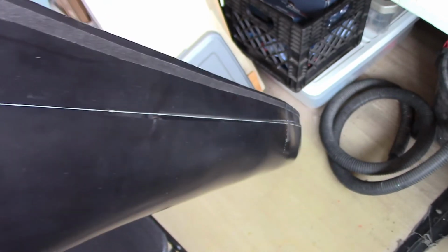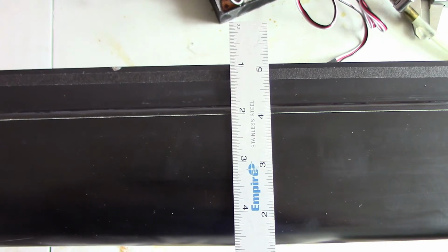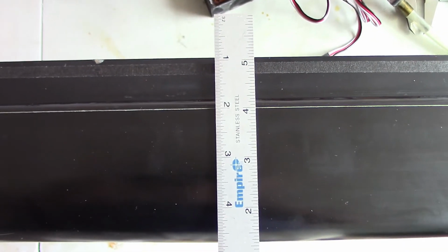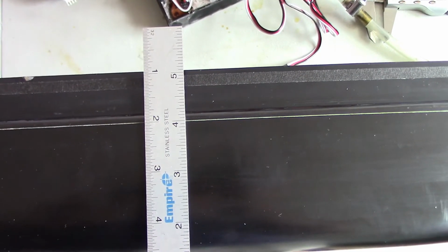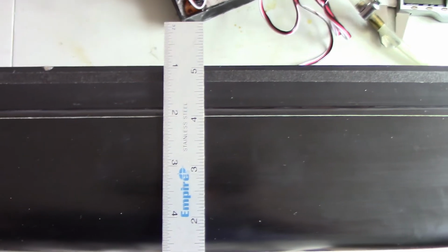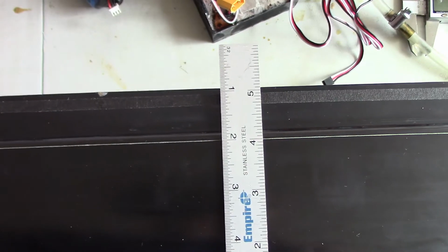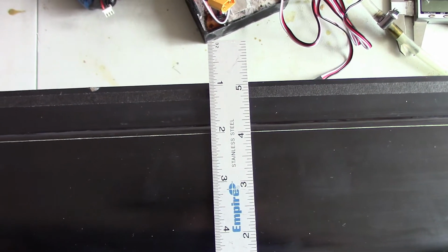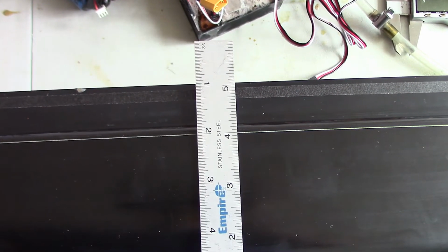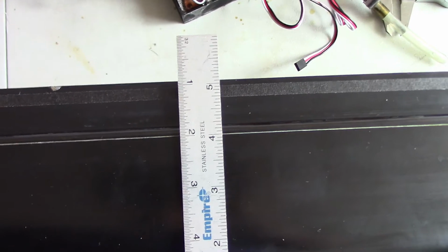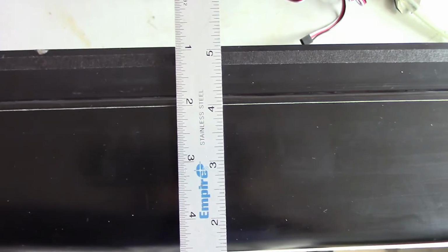So now that I have this, I'll mark out the bottom of the windows. To figure out the bottom of the windows along most of the hull, I think back to the rules. The rules say that you need at least 1 inch of penetrable area below the water line. And remember, the water line is a 1/4 inch thick, and if it's centered on where the water actually is, that would mean there's 1/8 of an inch of the water line that's actually below where this string is. So for a minimum distance from the string, that gives me 1 inch plus 1/8 of an inch, so 1 inch and 1/8.